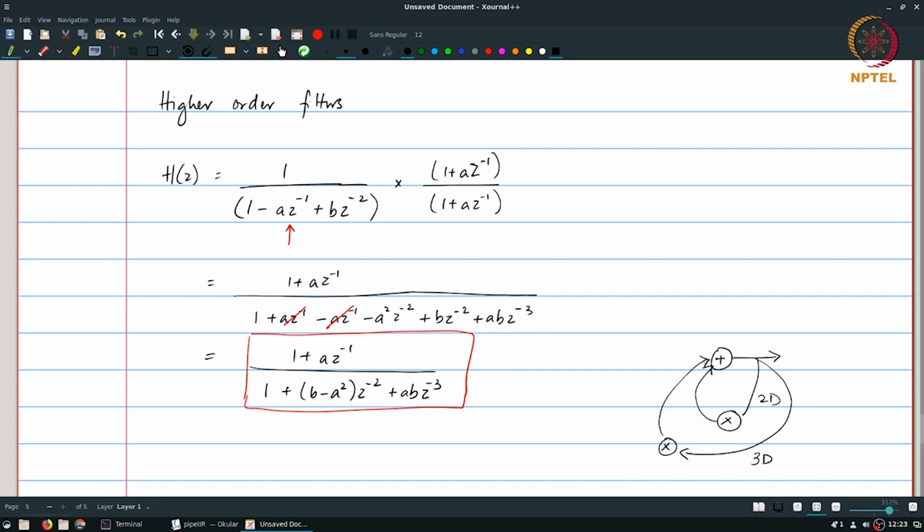Of course, this data flow graph has been intentionally drawn in this way, assuming that you just want to capture the effect of the delays. It helps to make it very clear that there are two loops involved here, and each of those loops in turn has a different value for the iteration period bound. The IPB for this one would be equal to (Tm + Ta)/2, and for the outer loop would be (Tm + Ta)/3, and therefore the larger value, (Tm + Ta)/2, is going to be the iteration period bound of the overall system.